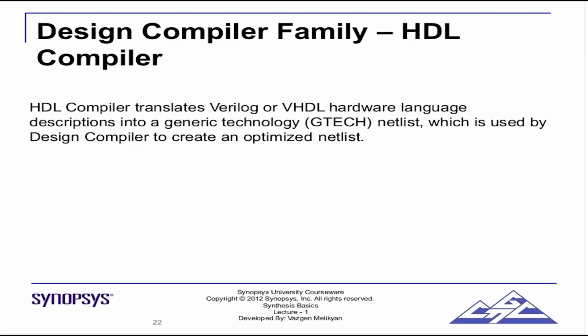Now this particular delay unit, #5, has nothing equivalent in hardware. Yes, we have buffers and inverters which will give some amount of delay, but saying #5 will not result in some hardware. That is, the synthesis tool will simply ignore #5.